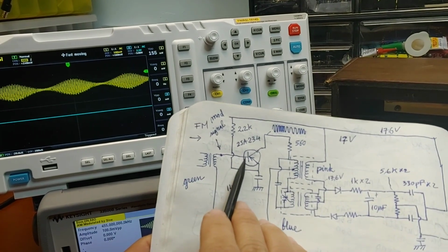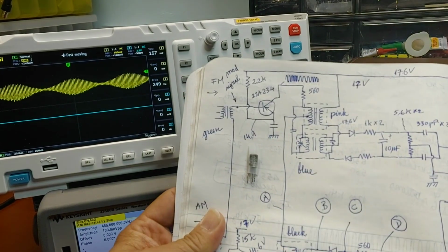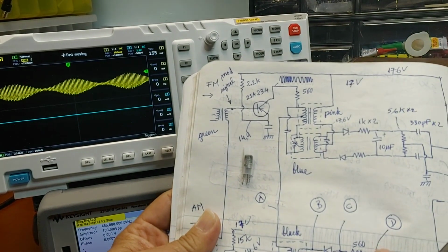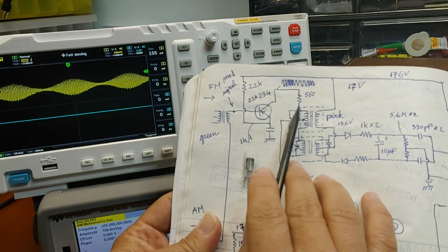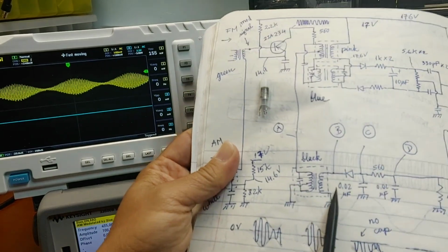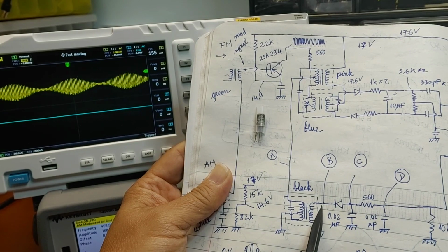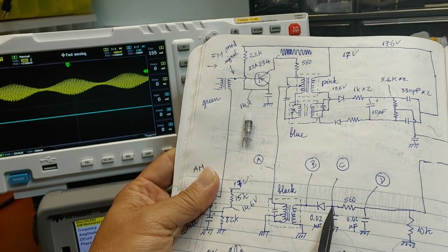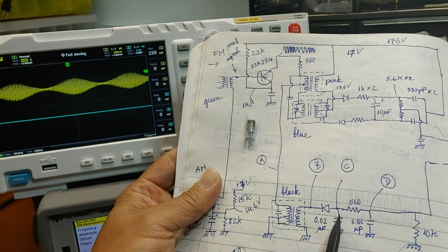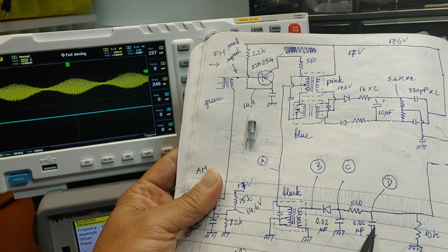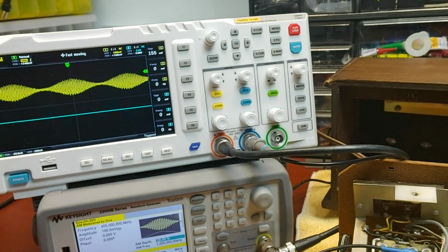And this is the pin B of this transistor, and this transistor is shared for both FM and AM IF amplifier circuits. And this signal here is amplified and goes through the connection of the coil and goes to the black transformer here. I'm going to probe at point B and point C. At point C, we have two waveforms to see, one without the capacitor and one with the capacitor. So right now I'm going to probe at point B for channel 2.